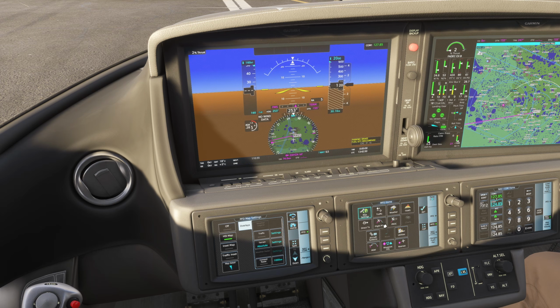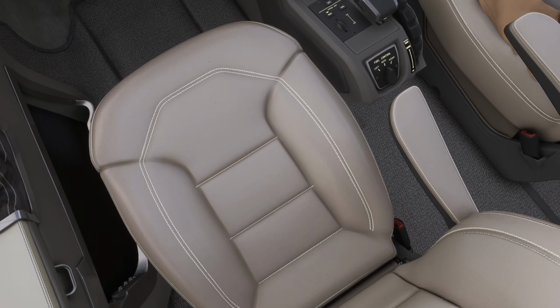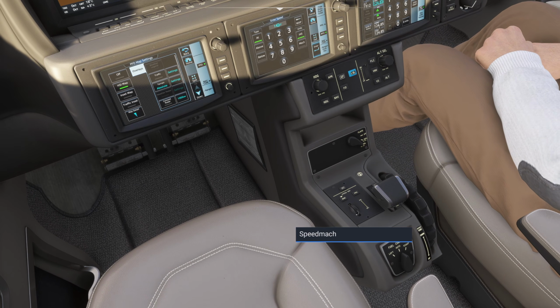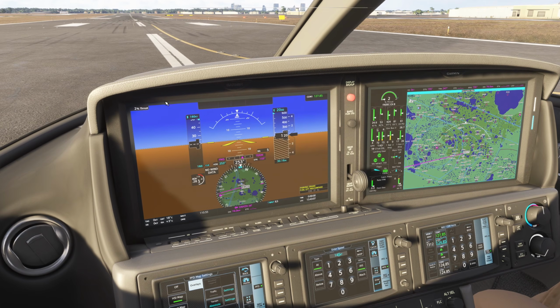Now I want to go back to our flight plan, and I want to manually adjust the speeds. So at Zaza we want to be slowing down to our approach speed, which is 140 knots. It's just taking the workload of us having to manage it ourselves by adjusting this manual auto throttle speed adjuster.